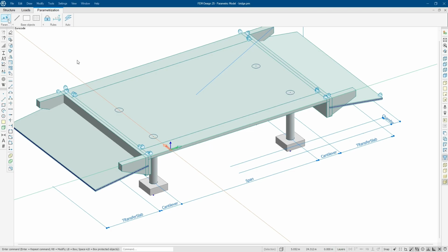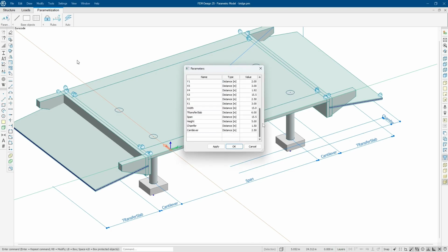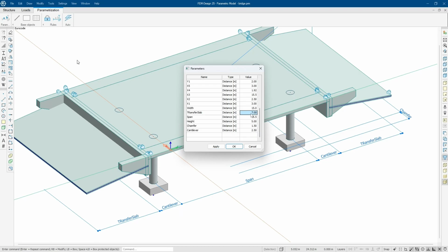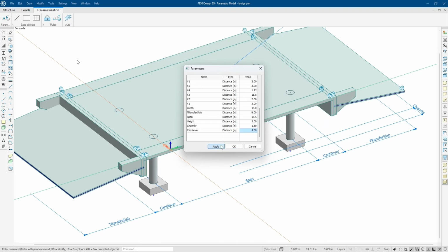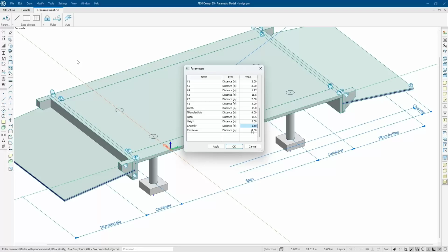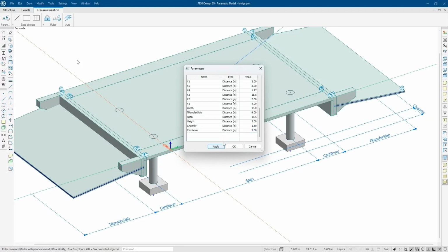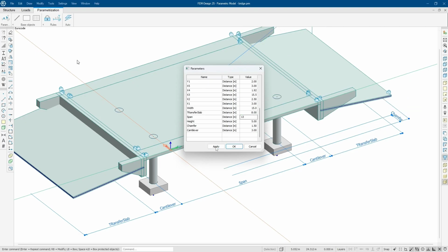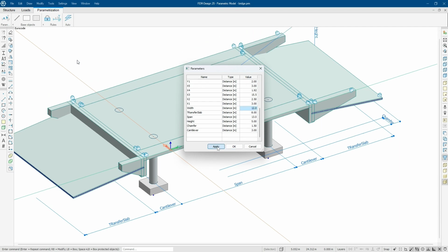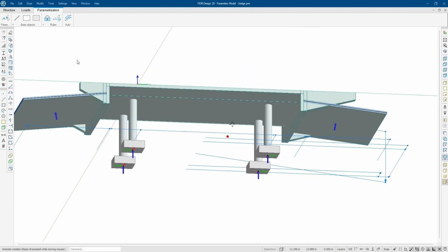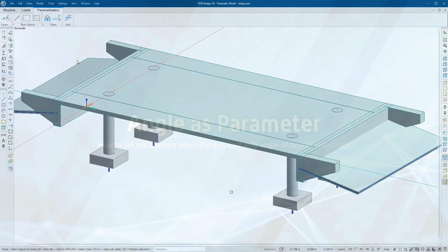So now this 3D block is ready. If you modify something, like the transfer slab, you can see that it now works how I want it. And if I modify the span length, the cantilever part of the bridge, the chamfer or anything else, it's now very logical. So now I can really quickly make one bridge model with all the supports, and it can even include loads, like basic loading. And it didn't take long to make this because I used the automation to define those parameters.